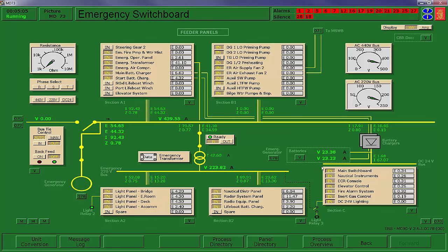All right, if you forget these, by the way, this main switchboard feeds power to the generator voltage controllers, and you will not be able to raise excitation, because if you don't have the battery charger on, that battery will discharge and you won't have the power available.